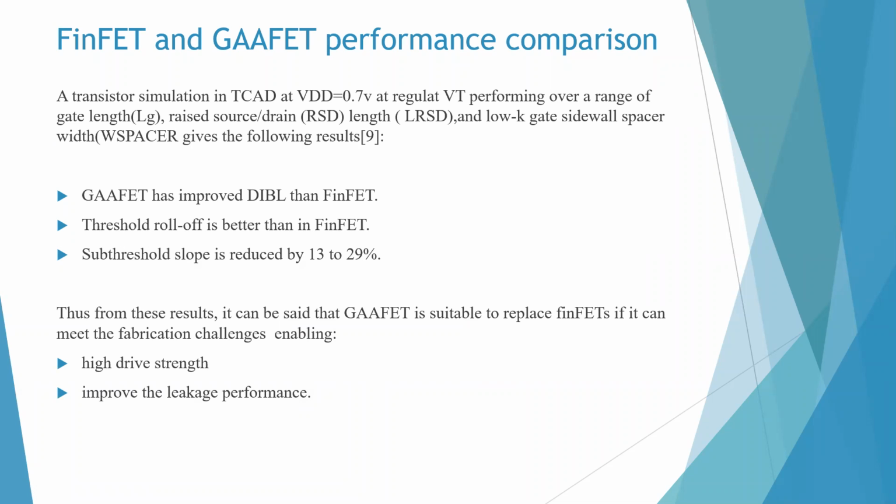So if we compare the performance of FinFET and gate-all-around FETs, from a paper where both were simulated with TCAD at a VDD of 0.7 volts at regular threshold voltage, gate-all-around FETs have improved DIBL performance compared to FinFETs.